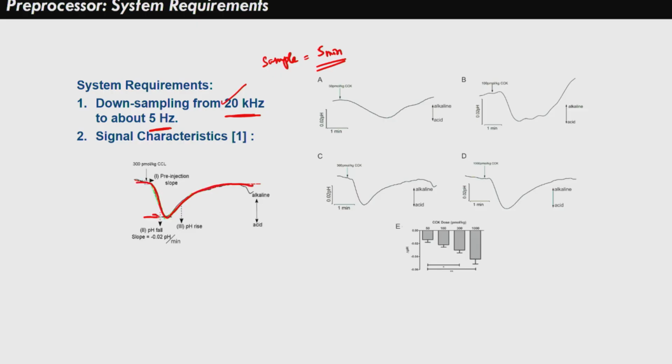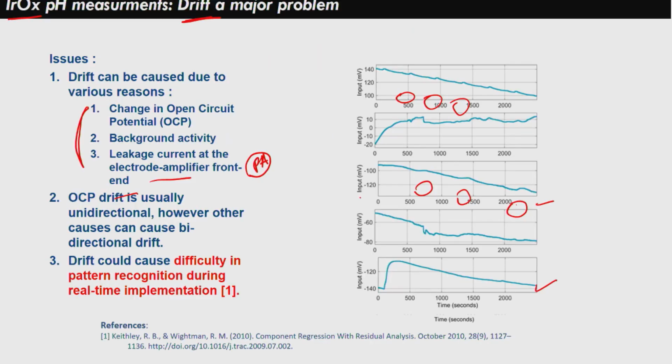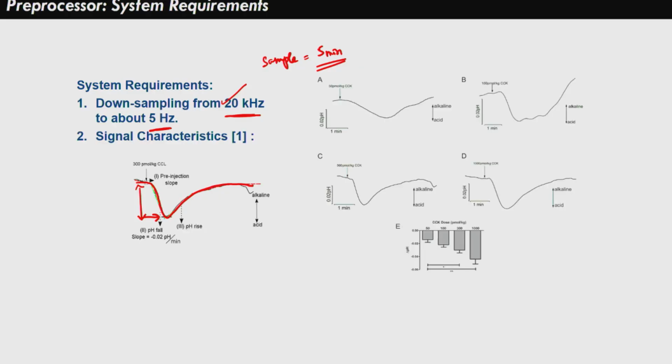So, this is in relation to the change in pH that happens due to an injection, and that we want to actually detect. This is inverted, because if we go back to the previous slide, this is a voltage signal, and the sensitivity is generally, as we saw yesterday, minus 0.075 millivolt per pH. So when you convert it into pH, the signal is inverted. If the voltage is increasing, that means the pH is going down. So that's why.